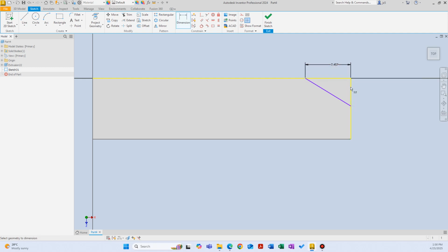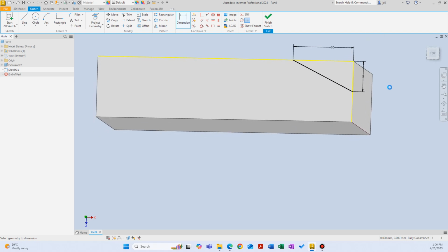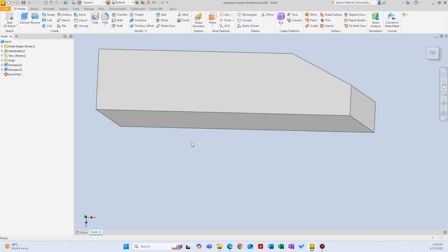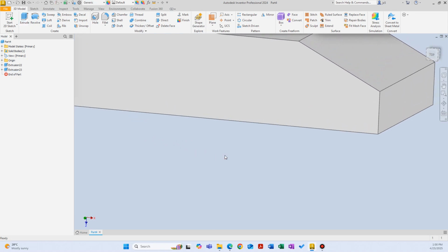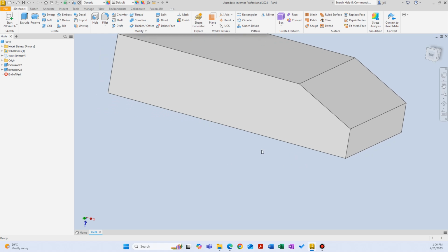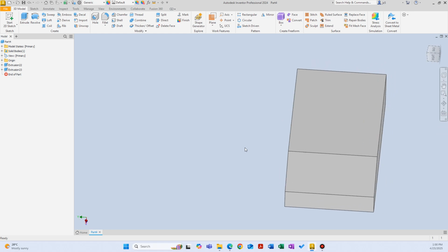Let's say this is 10 mm and this is 5 mm. Now 5 by 10 triangle is created here. Let's finish this 2D sketch and extrude that. Let's cut and through all so it removes all the material on its path. Now I created this kind of chamfer, this slant on this 3D object, but I took advantage of the existing designs. So now let's look at it in a different example.